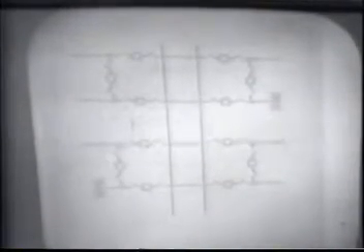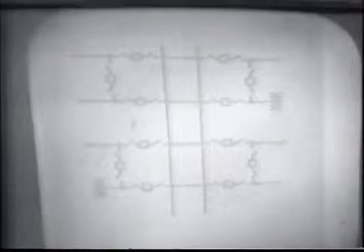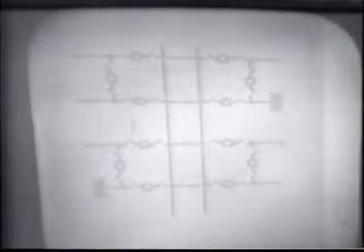We take up probably an equivalent amount of space that a ring bus does, but we do have another step up in reliability. With the ring bus, it is possible to have two breakers open at some time, which could divide your bus into two sections, which could be undesirable from a system operating standpoint at some times.